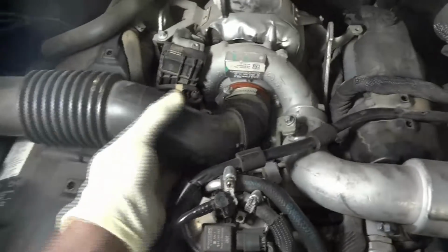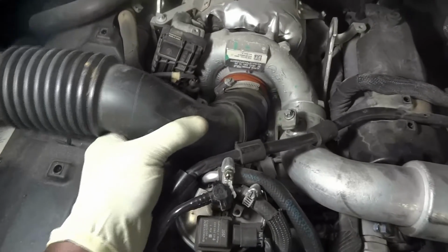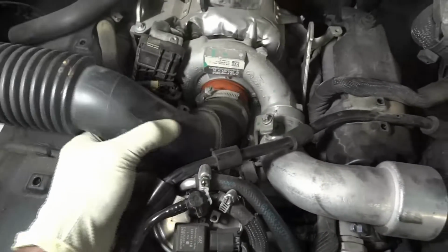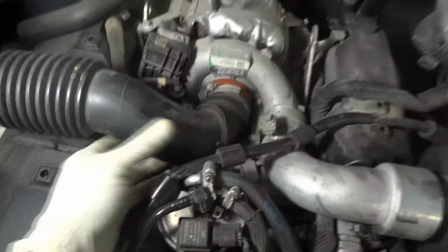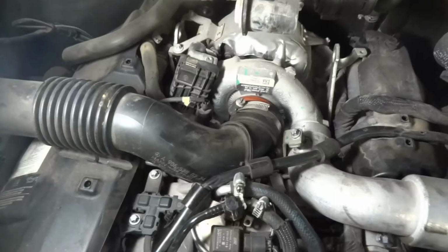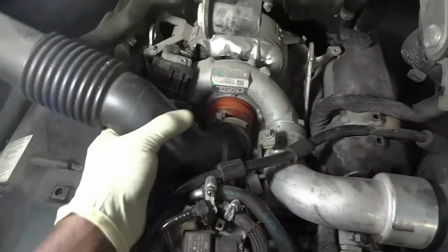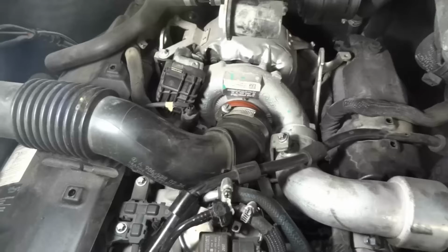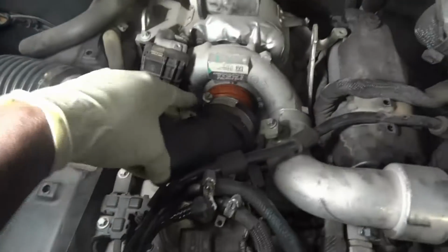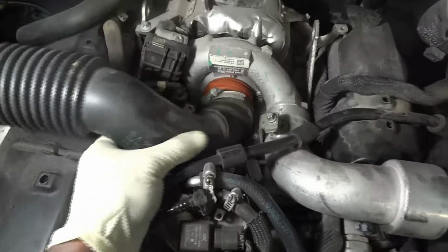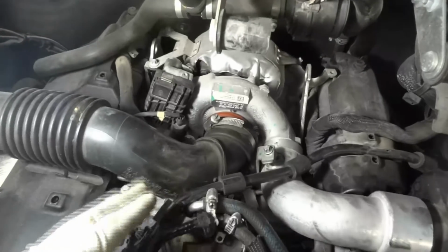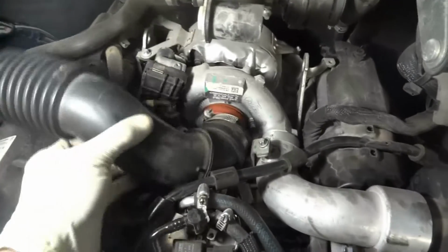So I believe this was slightly off. I mean, it wasn't off completely, because if it were before, we would have heard it while I was revving the engine. So once I removed the air filter box, I guess this thing just popped off. So what we're gonna do is, I'm gonna look at this gasket and make sure it looks good. I'm gonna put this back and tighten it and clear the code, and then we're gonna go on a test drive and see if these codes will come back up. So I guess that's all it was.